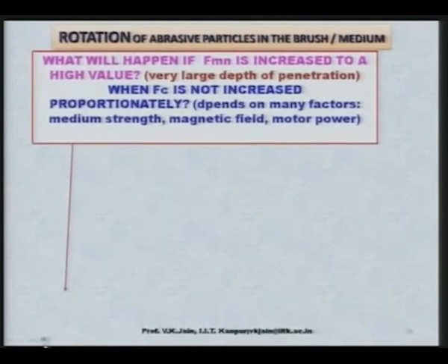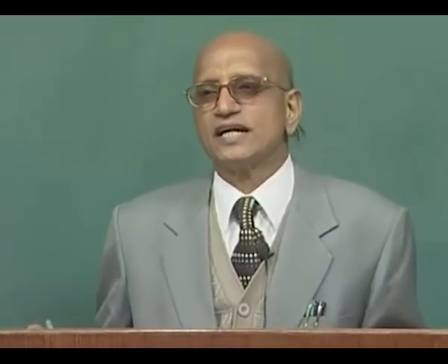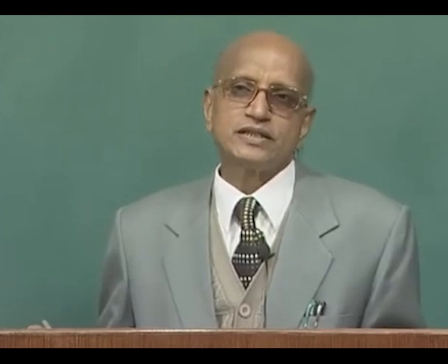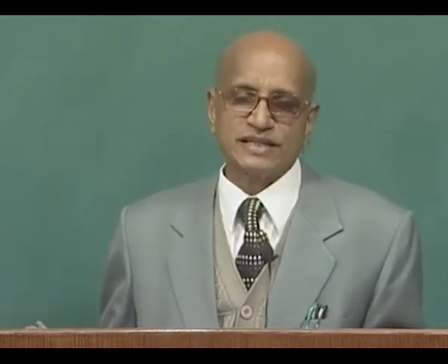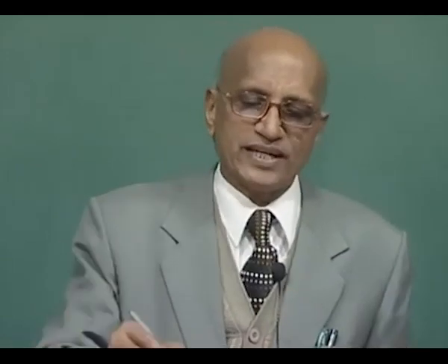Now, what will happen if the normal magnetic force Fmn is increased to a higher value? As I mentioned earlier, we have already seen the observations made during pulsating magnetic abrasive finishing, where the normal force increased to 3000 Newton from 70 to 75 Newton in the case of a smooth DC power supply. So, with such a large value of normal force, definitely the depth of penetration is going to be very large.